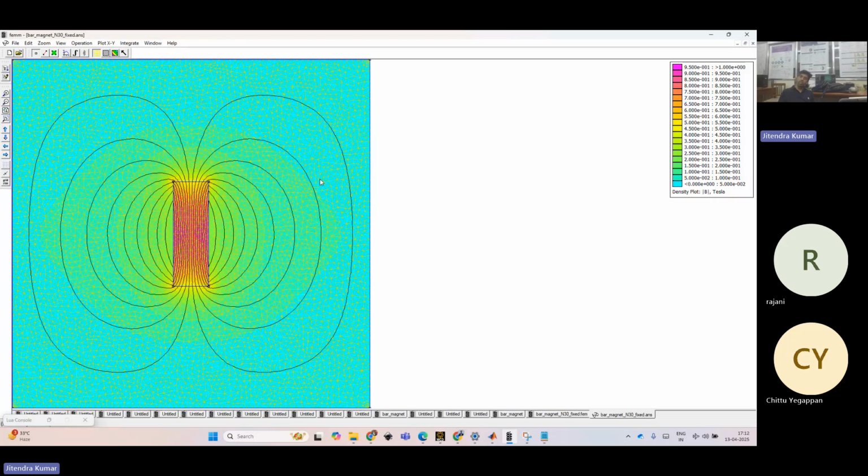Anyway, we are going to discuss. Just try to simulate something circular and try to simulate some model, like surface mounted or so. Or if you are not very comfortable with the scripting, you should try the options of drawing the curves and all. That should also be similar to the CAD drawing. So we will see if any assignment questions are there. Otherwise, we will continue with this FEMM and the concepts behind boundary conditions like Dirichlet, Neumann, all, as I said we can consider.